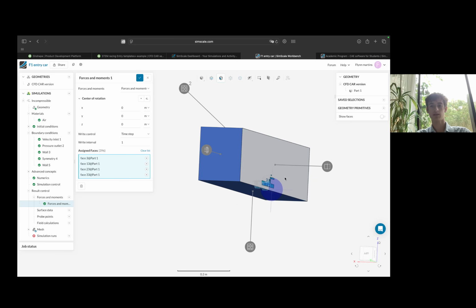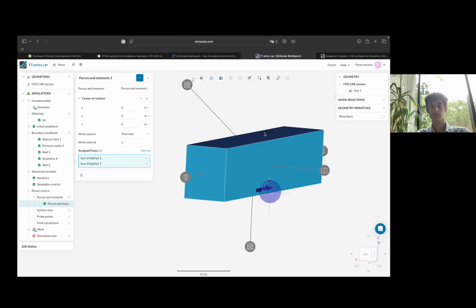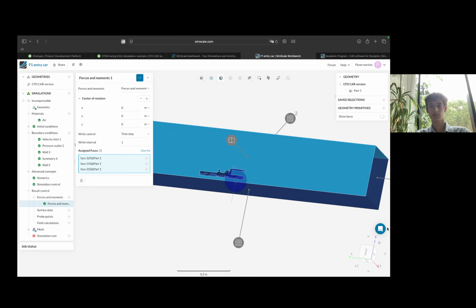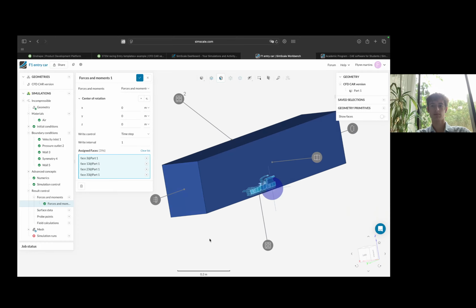And that's on all of these here. So just once again, in case you didn't catch that, select all these faces. That one, that one, that one. Left click, invert assignment. Okay, that's quite important because you won't be able to see the results if you've not selected this correctly, which will be annoying because you have to do the thing again.